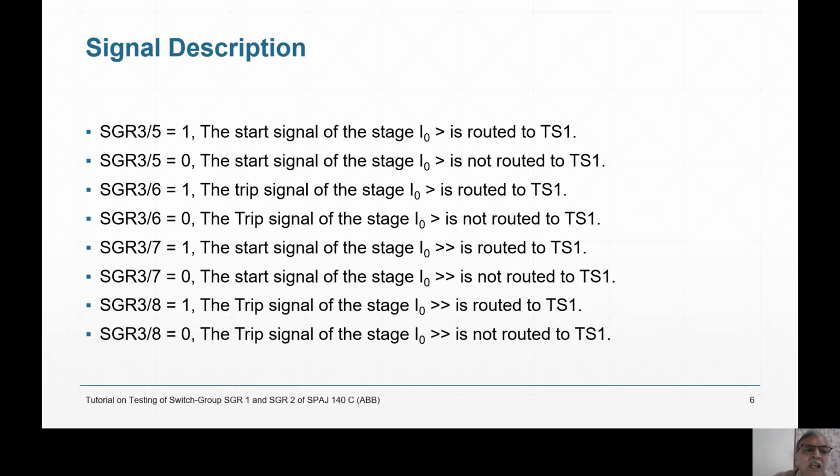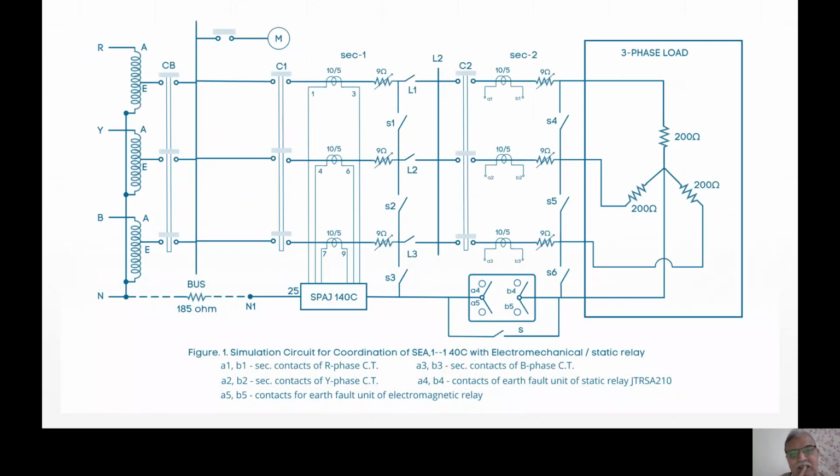So like that, two different relays are actuated, and when two different relays are actuated, they will give signal to two different breakers. Relay is same, and you are tripping both breakers at a time, right? Relay is same. You are not changing the relay. By same relay, you are sending the signal to different breakers.